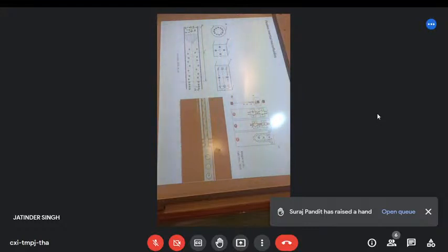So here there's the lift forces from the wall positioning the particles at a certain prearranged position as done in this table here. So we've got a certain flow velocity distribution with a quasi flow going through our channel, which means that we get pressure gradients along this uneven flow. We get lift push away forces from the wall, and we get at the same time shear forces because the velocity here is higher than there. We get a bit of spin. And you can see that the particles, after some distance, they start organizing themselves about a quarter of the channel away from the wall. And if they come out, you can collect them in droplets.